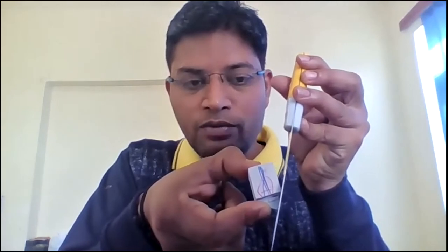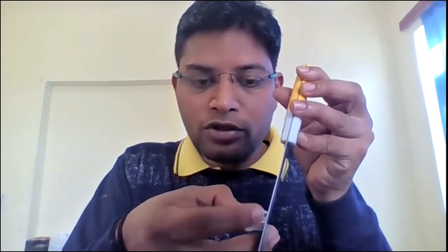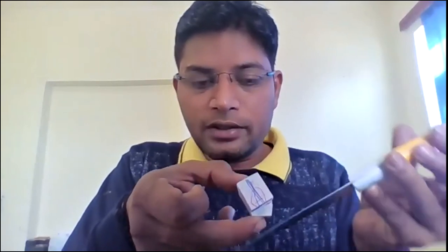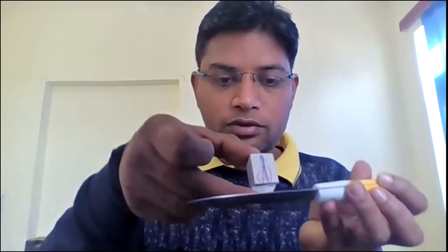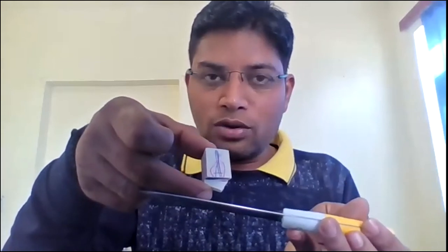But now we have tilted this plane, so we define it as the auxiliary plane or cutting plane, because in this plane only is the cutting edge, and because of that the material will be removed. Perpendicular to that, another plane is the orthogonal plane.